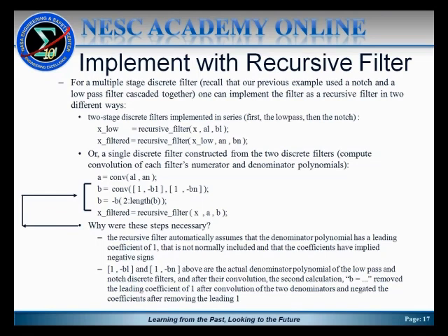Recall from part 1 of this presentation that one of the features of convolution is that it can be used to multiply two polynomials together term by term. So in addition to the other uses of convolution that we have demonstrated in digital signal processing, it's also very useful just to multiply two polynomials.